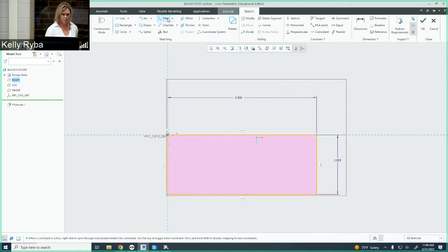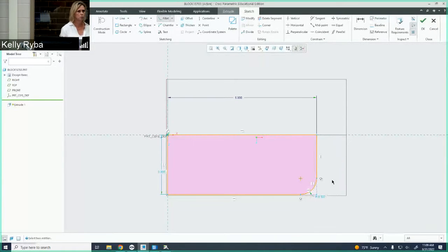So I've got a fillet command right here, and there are options underneath, okay? But I'm just going to use the standard circular fillet, and I'm going to grab one of the lines and then the other, and it's going to put it in there for me and assume a dimension, okay? Now, once I middle mouse button, I can double click on that dimension and change it. So the middle mouse button kind of sets it, right? Ends the command, if you would.